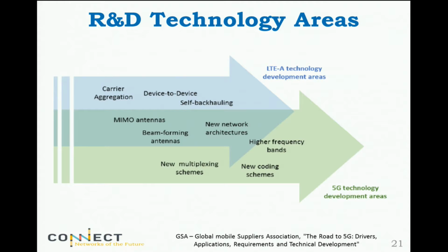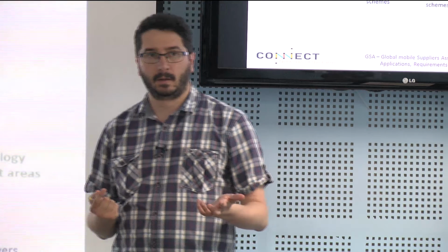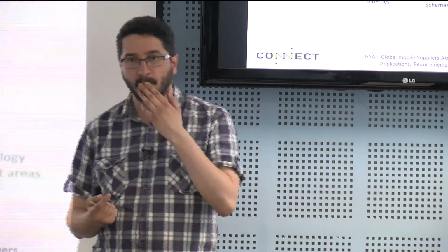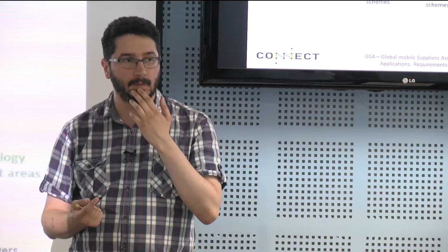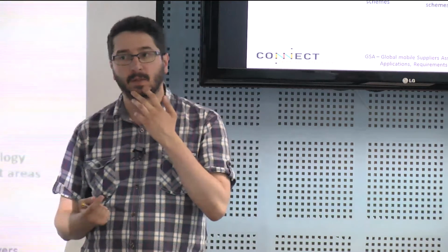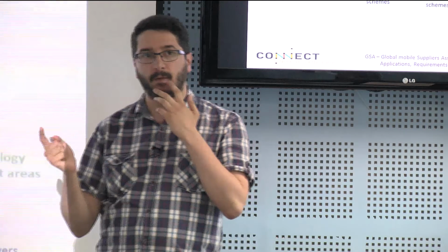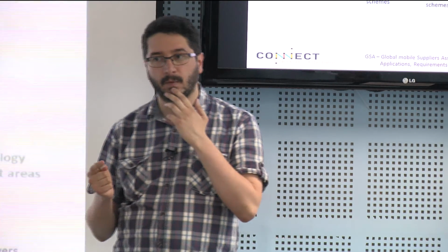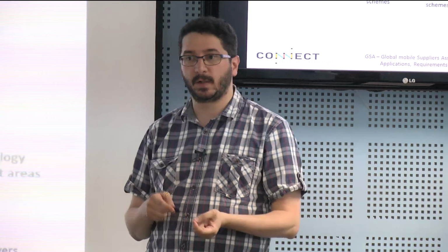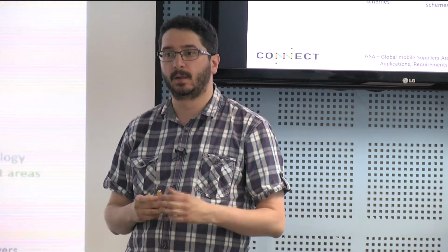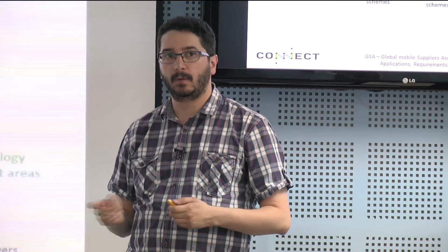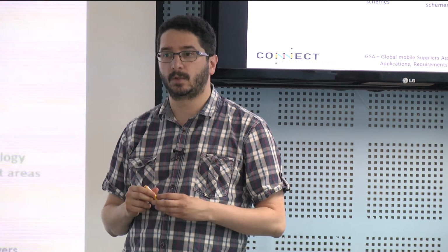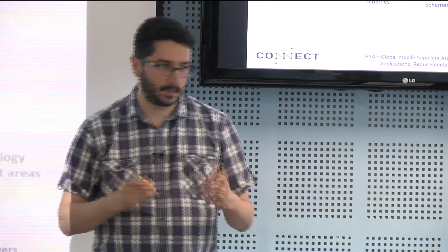And of course, you do have coding also in the sense of space coding. So you do have pre-coding schemes for massive MIMO. The normal ones people are talking about are zero forcing, maximum ratio transmission, generalized zero forcing. The bound is given by a scheme which is called dirty paper coding. Dirty paper coding, though, is very complex. So it gives you a bound, but normally, at least in downlink, I think the normal choice is to adopt zero forcing, for example.